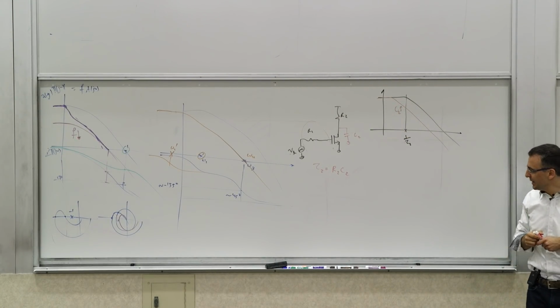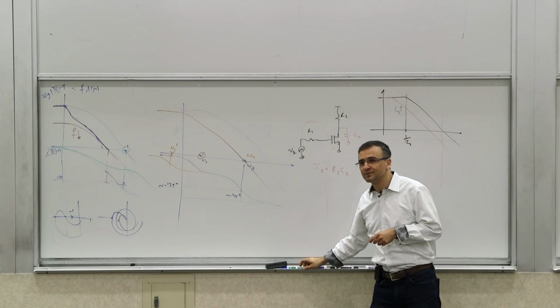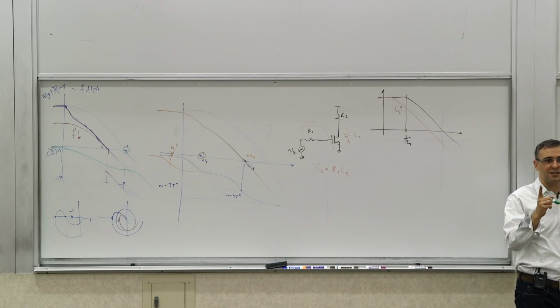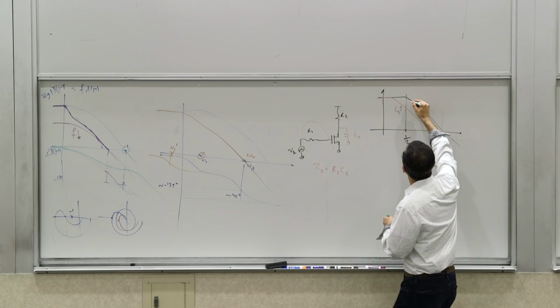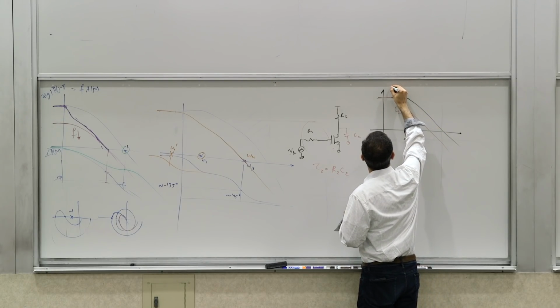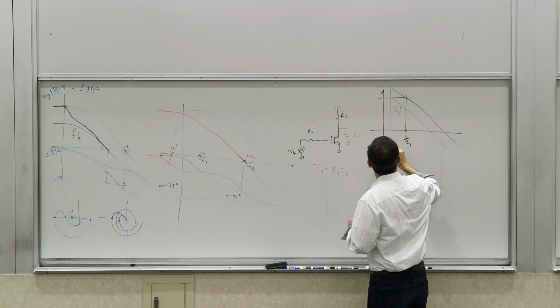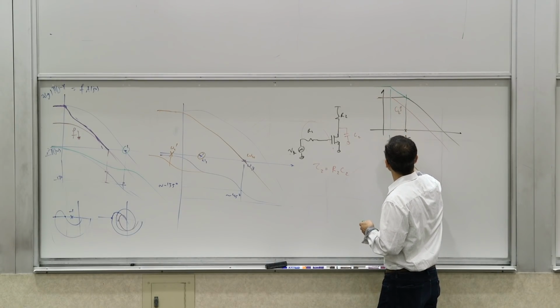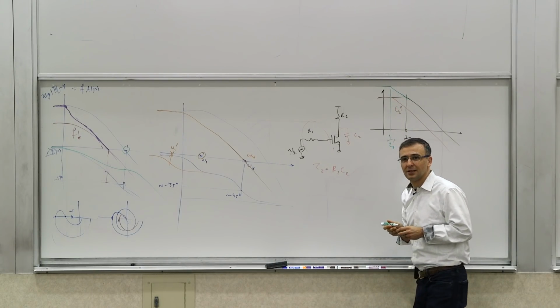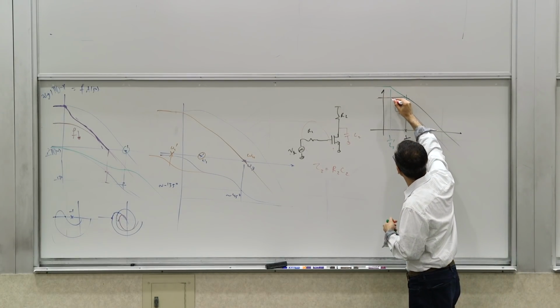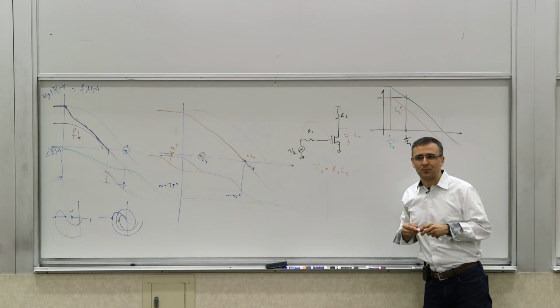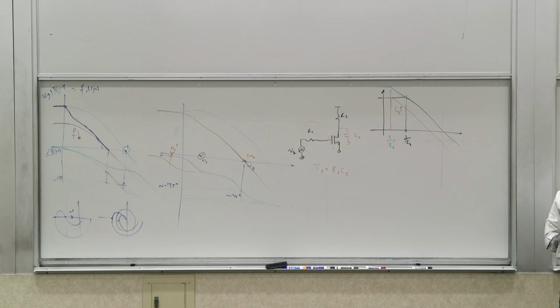Now what happens if we increase R2? Well, the time constant goes up by the same factor, but the low frequency gain also goes up. So instead of that, this is what will happen. You will get a new time constant, 1 over tau 2 prime, which is the same as the one you got when you increased the capacitance by the same factor. But is this doing what we are expecting it to do?